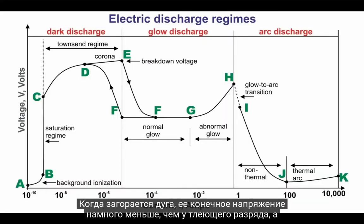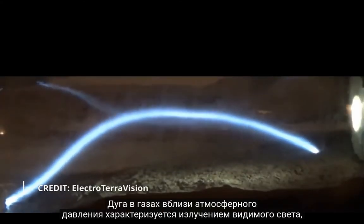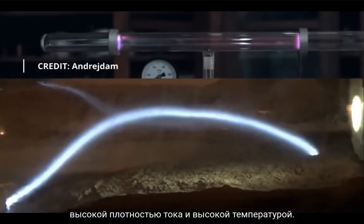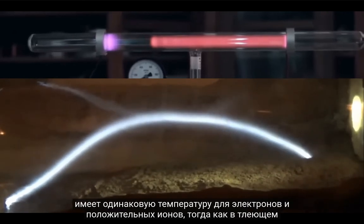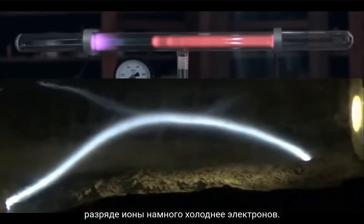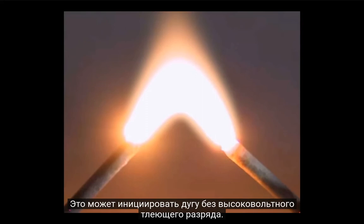When an arc starts, its terminal voltage is much less than a glow discharge, and the current is higher. An arc in gases near atmospheric pressure is characterized by visible light emissions, high current density, and high temperature. An arc discharge is distinguished from a glow discharge partly due to the fact that it has a similar temperature for the electrons and positive ions, whereas in a glow discharge the ions are much colder than the electrons. A drawn arc can be initiated by two electrodes initially in contact and drawn apart. This can initiate an arc without the high voltage glow discharge.